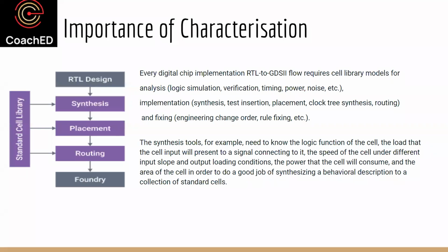Better modeling is happening. You can now improve the accuracy of the models with respect to SPICE, and also with newer types of transistors and more complex phenomena showing up in the process, we have more and more complex effects being captured in the characterization.